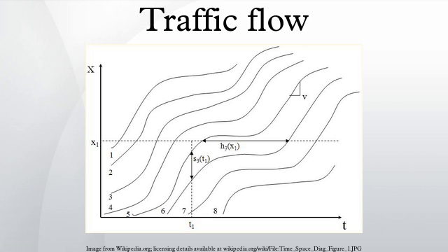Variable speed limit assignment. This is an upcoming approach of eliminating shock waves and increasing safety for the vehicles. The concept is based on the fact that the risk of accident on a roadway increases with speed differential between the upstream and downstream vehicles. The two types of crash risk which can be reduced from VSL implementation are the rear-end crash and the lane change crash. Different approaches have been implemented by researchers to build a suitable VSL algorithm.